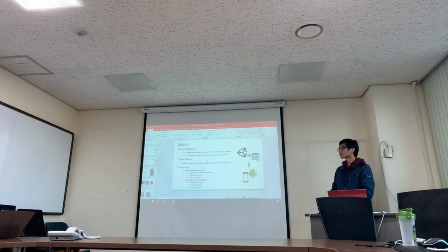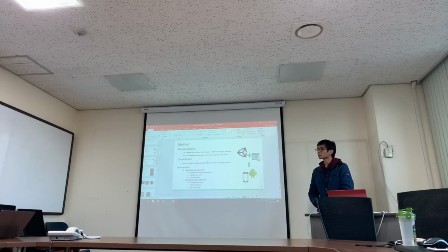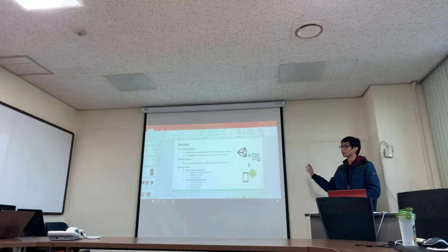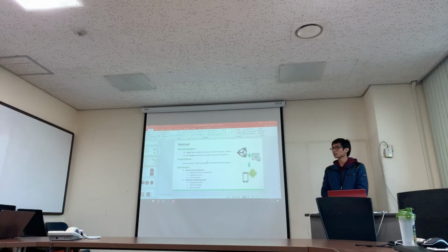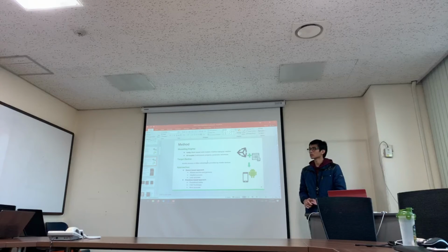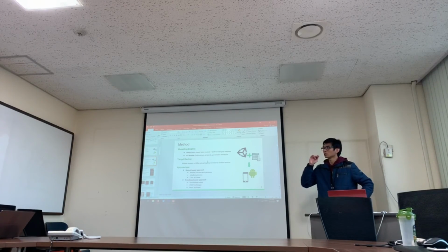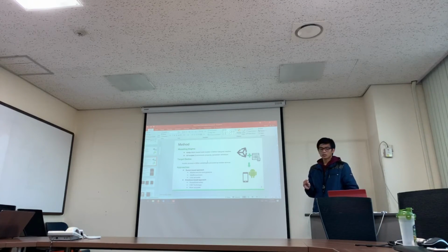One question. In general, you are saying Unity is based on mesh, but how do you use primitives? You enter only 3 numbers for a cube, right? Yeah, and those 3 values are the only thing you need to define a 3D cube mesh. And the data structure of a primitive is CSG rather than mesh. So mesh is used only for display. Is that right? In the case of GDI, predefined models are also meshes. So it displays a mesh, not stored as a mesh. Storage is only 3 numbers, right? So this is solid-based.